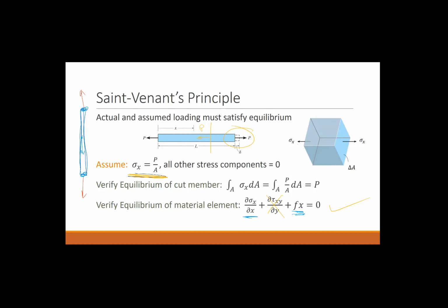So you have the volume times the density, or the mass per unit volume. So you have the whole mass, or the whole weight, acting down. And if I were to go to any point in between, I'd get some linear value. It's going from 0 to the maximum weight. Would you agree? Okay, so in reality, what's happening is you don't have a constant stress state. Due to that loading, you have a constant P over A throughout, but then you have that small effect of gravity